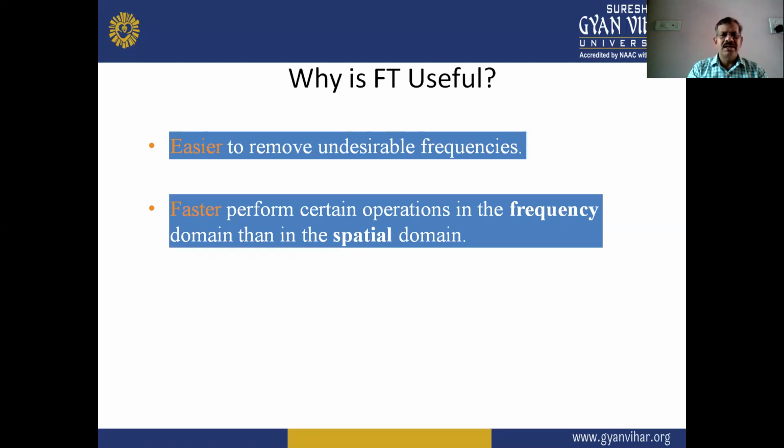So why is the FT useful? First, it is easier to remove undesirable frequencies with the Fourier transform. Second, it is faster to perform certain operations in the frequency domain than in the spatial domain. So due to these two reasons, the Fourier transform is useful.